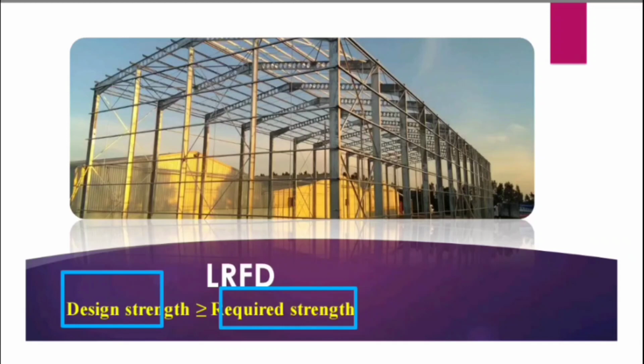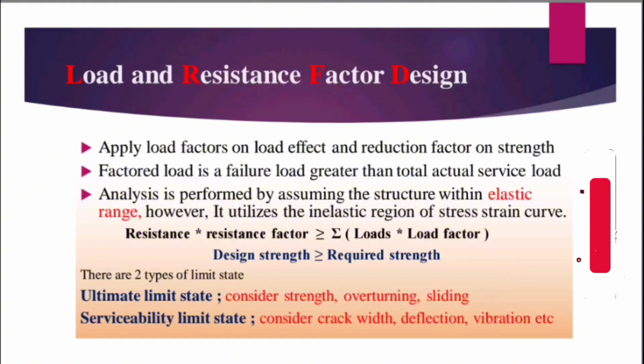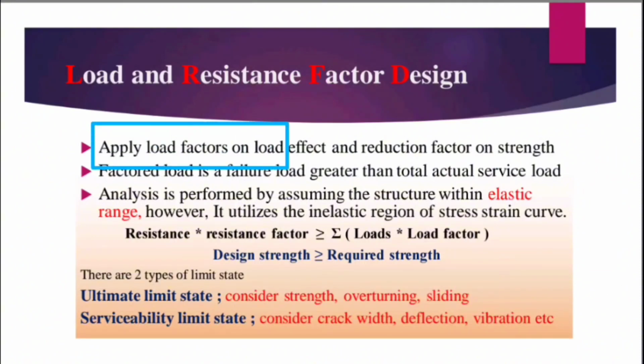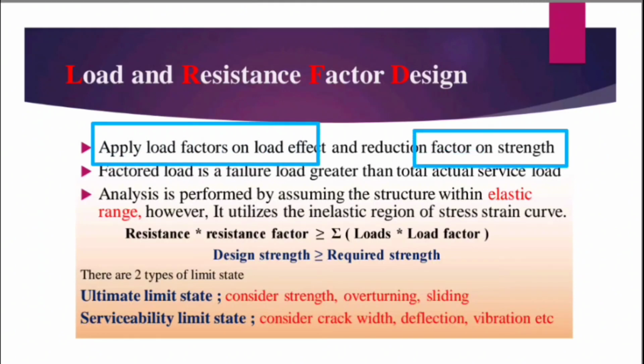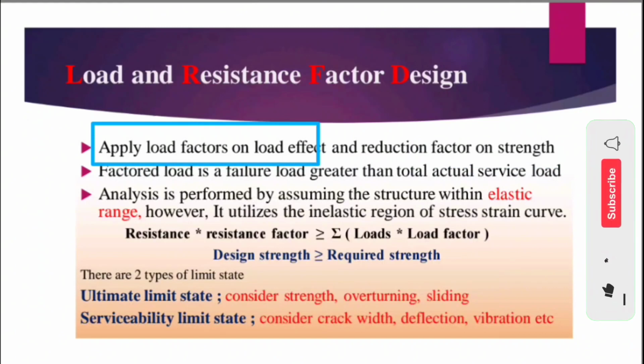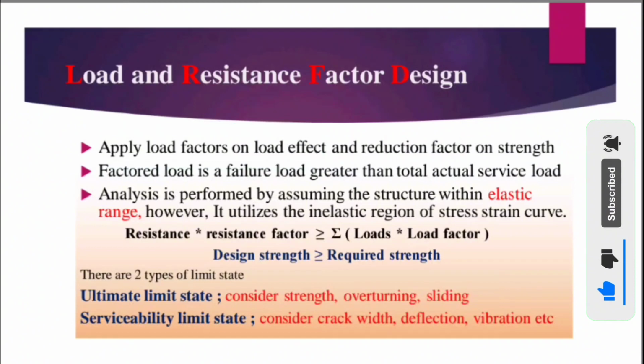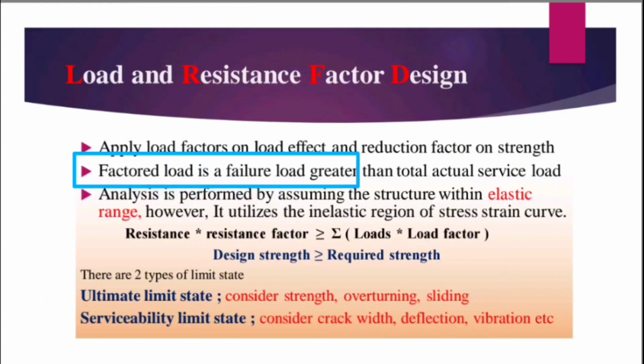Since you know the basics of LRFD, the load and resistance factor design, we will apply the load factor on the load effect side and the strength reduction factor on the strength capacity of a member side of the design equation. So we will be amplifying the loads and reducing the strength, due to which we will achieve the design equation and the structure will be safe and strong in every term of serviceability or safety.